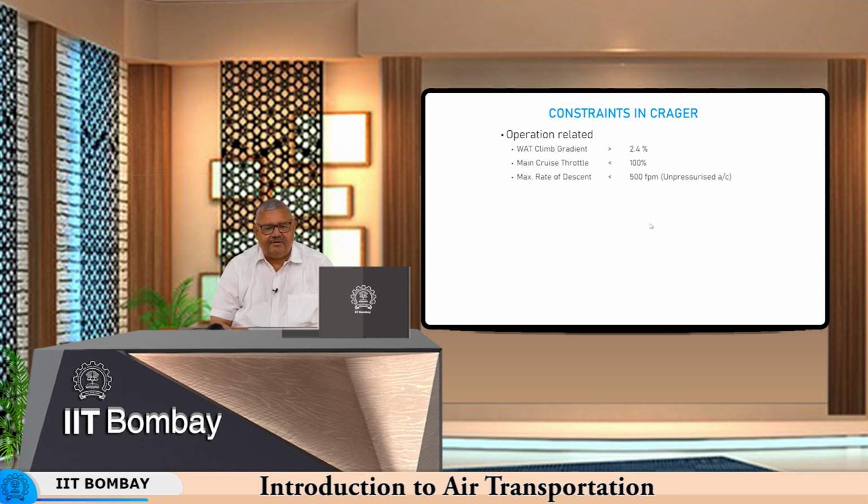Because the aircraft is unpressurized, we put a constraint that the maximum rate of descent will be 500 feet per minute. This number comes from industry practice and from a survey of literature on what rate is being followed by contemporary unpressurized transport aircraft.